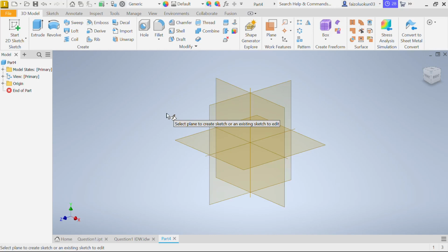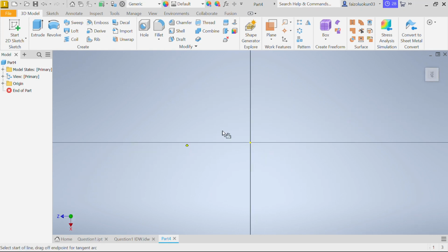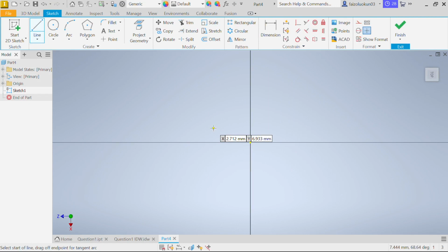Question two shows a cylinder penetrated by a square prism. It asks to draw the views and the complete elevation with the interpenetration curve and an end view, in the direction of the arrow. So now we're going to start with the cylinder.